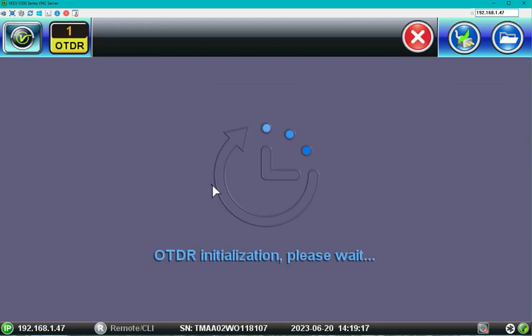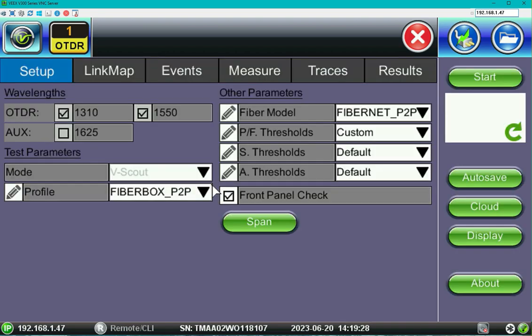The idea behind having different pulses is that one single pulse might work for a certain distance, a certain configuration, while a different pulse width might work for a different configuration. Let's take, for example, a very short link distance, let's say 10 kilometers. If you're using a short pulse, that would be sufficient. But if you have a link distance of about 100 kilometers, then you need to use a pulse width which can reach the end of the link.